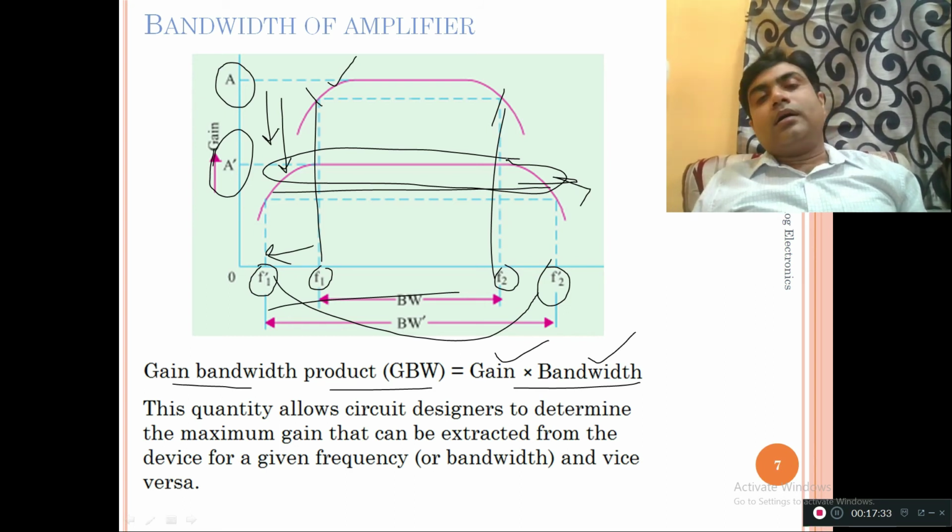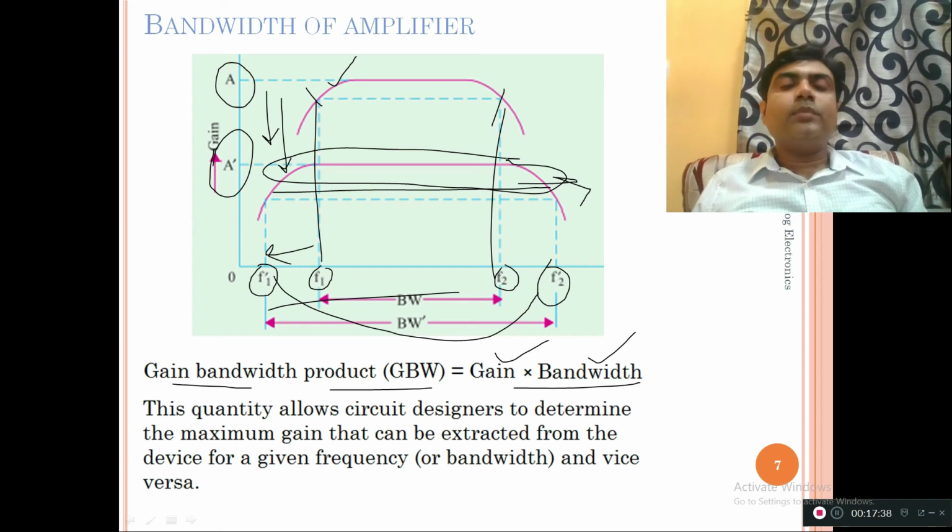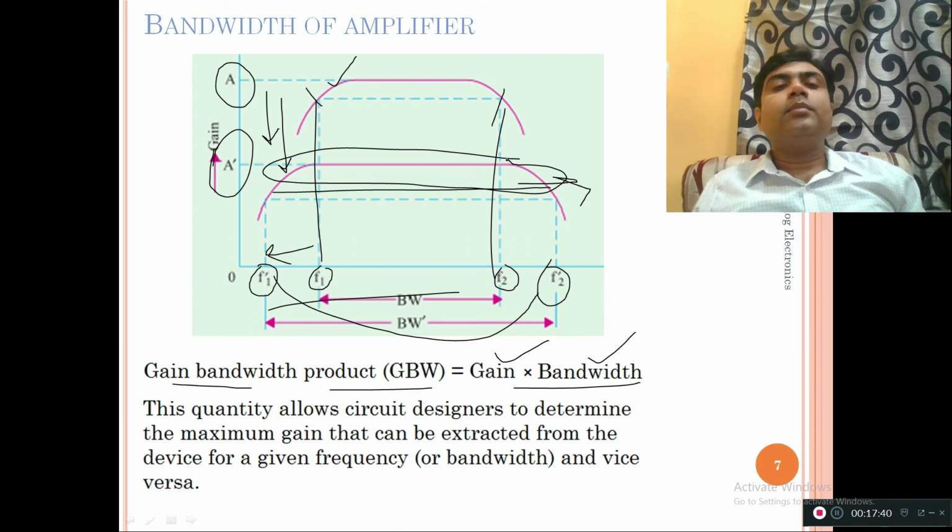So the next effect which we have seen is that negative feedback gives me a higher band of frequencies. It improves my bandwidth so that I can have the performance of the amplifier, that is the gain of the amplifier, to be constant, or stabilized over the wider band of frequencies. So this is the second outcome.